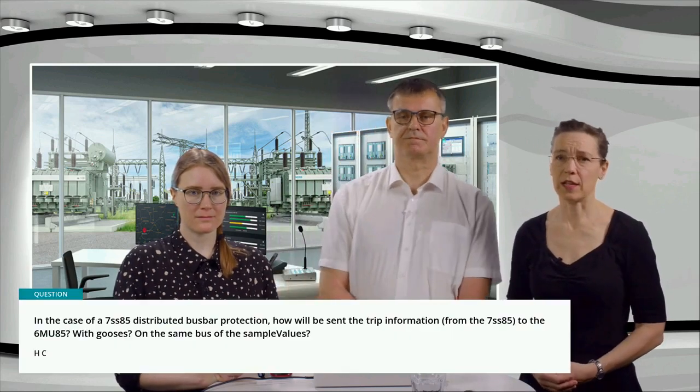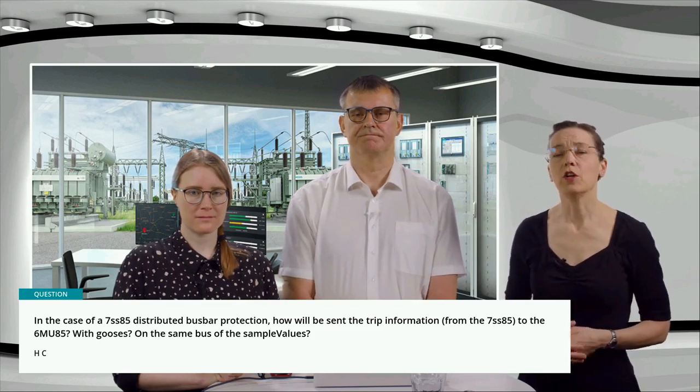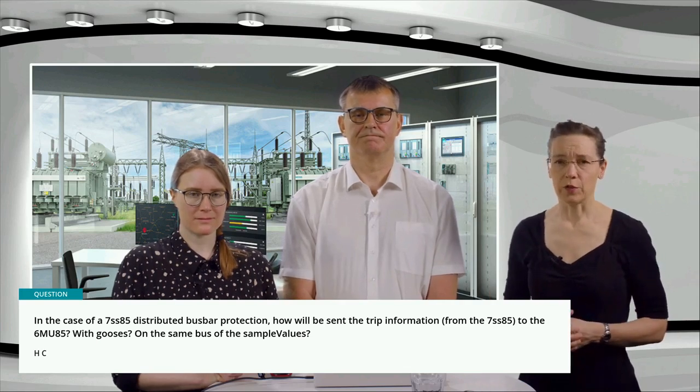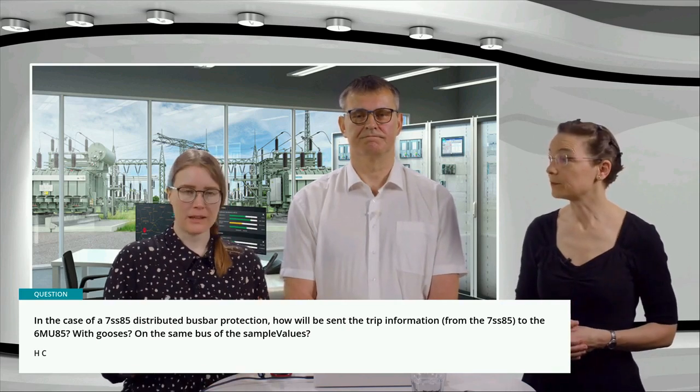And then the next question came in from HC. In the case of a 7SS85 distributed busbar protection, how will the trip information be sent from the 7SS85 to the 6MU85? Will that be done with GOOSE, or will it be the same bus configuration as the sampled values? For the 7SS85CU solution, the exchange of binary signals is not done via GOOSE.